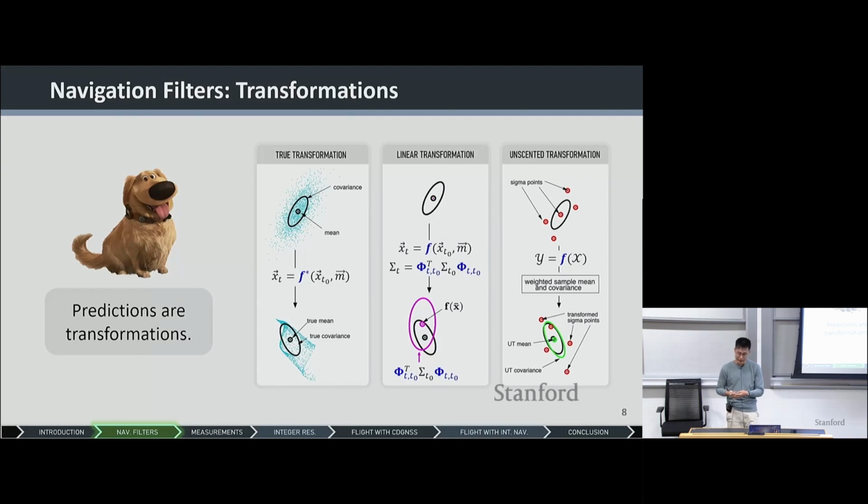More recently, in the last 2 decades, people have been adopting unscented Kalman filters as well. Unscented transformations do away with the linearization step. They ask what are the strategic data points that I want to select so that it preserves all that knowledge I need to reconstruct my distribution if I were to do some kind of a nonlinear transform on it.